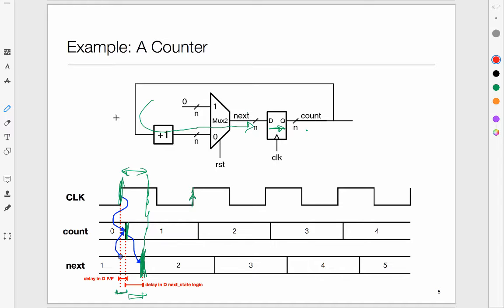You might also imagine another situation, where I'm sending the data to some other flip-flop far away on the chip, and the clock at that flip-flop may not arrive at the same time as the clock did in my system. So I can also run into the reverse problem: I was hoping this data would reach after the clock tick, but it actually reaches before the clock tick at the remote end. So you can have both problems in both directions, because clock is also a signal, travels over wires, and wires have delays.